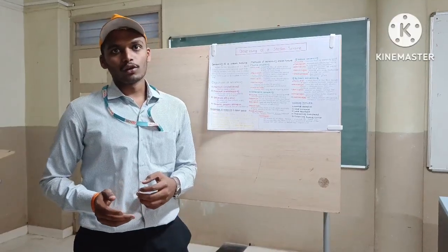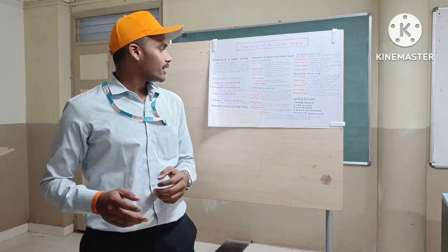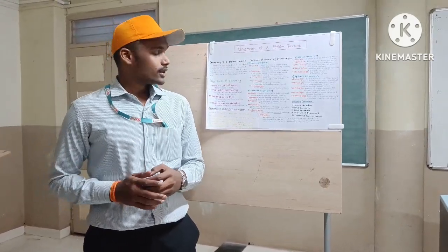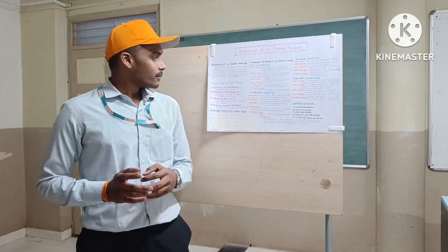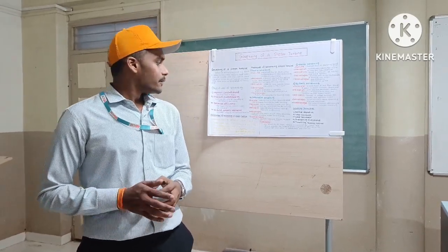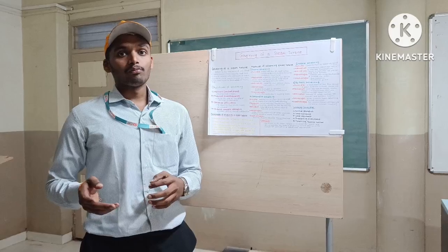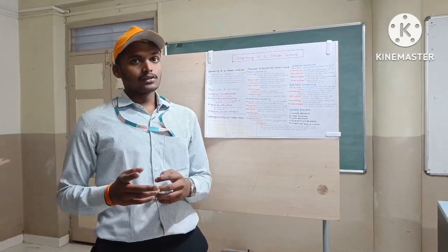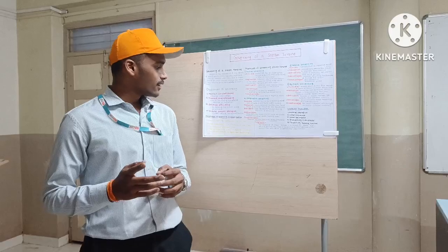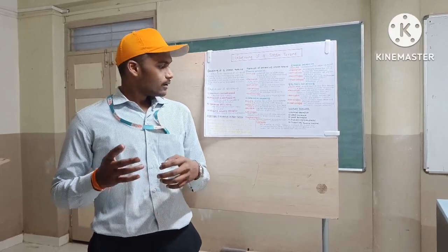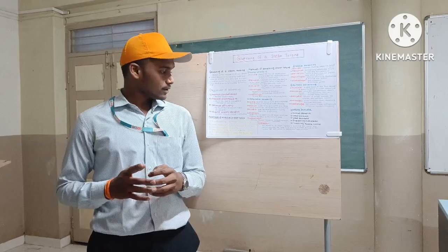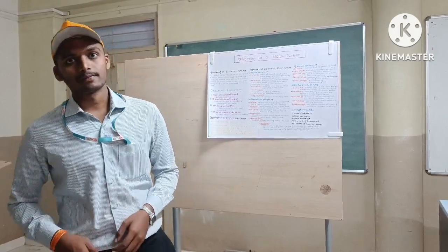There are four objectives of governing. First, maintain constant speed despite load changes. Second, prevent overspeeding, meaning prevent damage. Third, optimize the efficiency by adjusting the steam as needed. And fourth, ensure smooth operation under varying operational conditions.